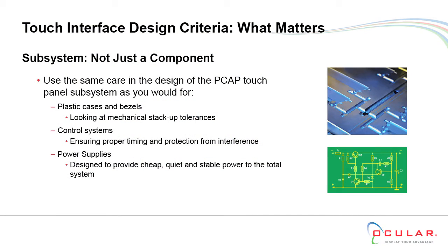Projective capacitive touch functions with electrical fields. They're fragile. They're simple, fragile, projected fields. They're impacted by environmental situations: water, other fields coming off your power supply, noise in the system. It's again very critical.